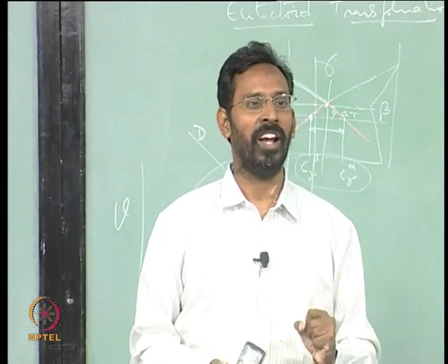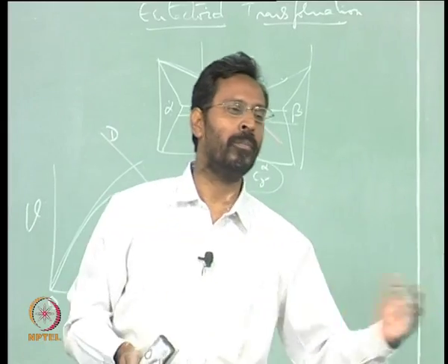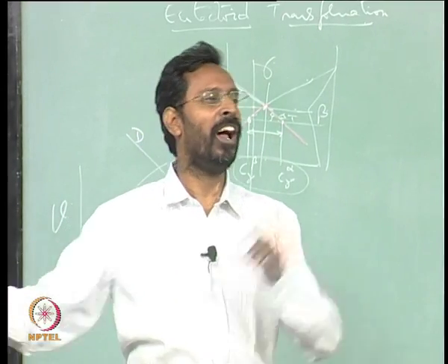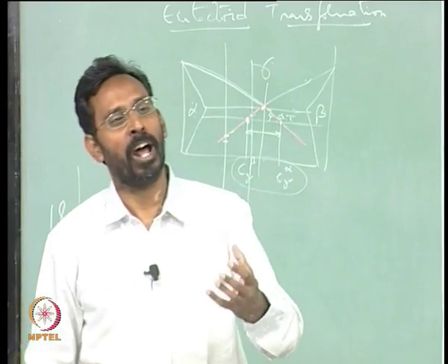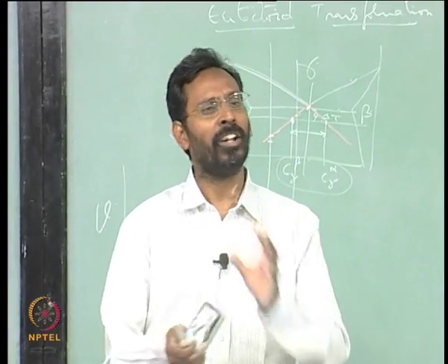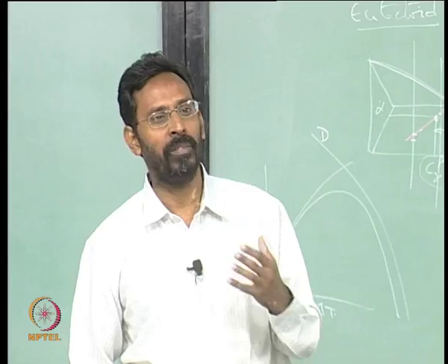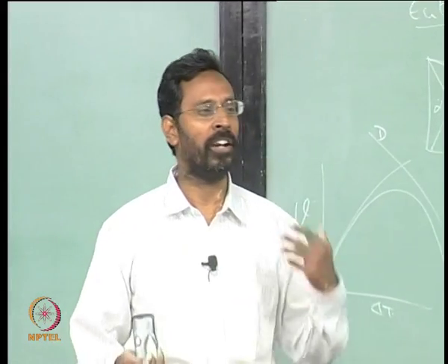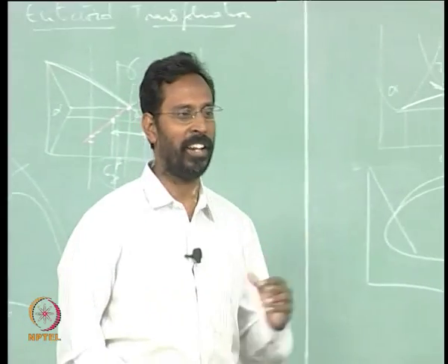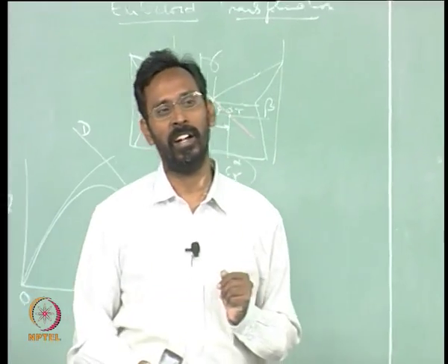And if I see 20% and go back and calculate from the lever rule and say, because it is 20%, its composition is, let us say, 0.5 or so, you are making an error. The actual composition, if you do chemical analysis, will not correspond to that. The reason is I have taken a normalized steel. In a normalized steel, the volume fraction of the ferrite phase will not correspond to what is decided by the phase diagram. So these are the minor issues you have to be very clear about when you want to utilize microstructures to understand the composition, because many people may not have chemical analysis facilities, so we tend to simply see the microstructure and get an idea of the composition.